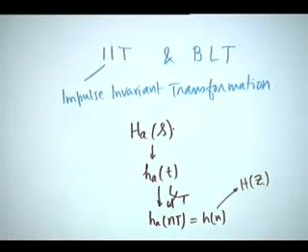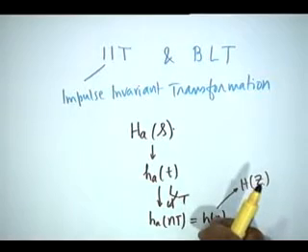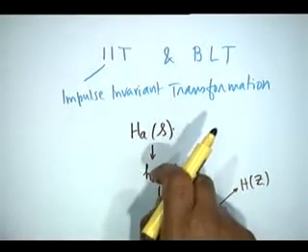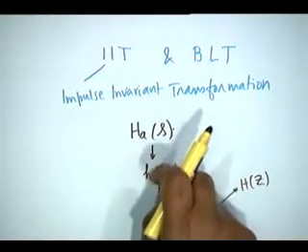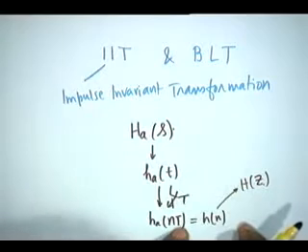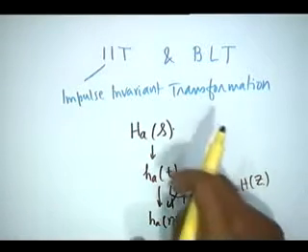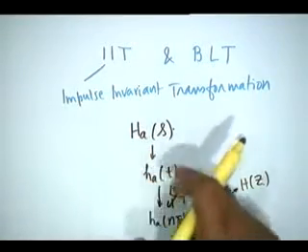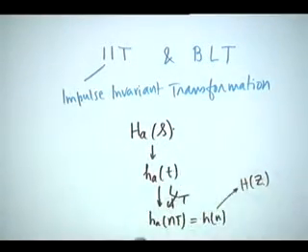That is, the digital filter impulse response is the sampled version of the analog filter impulse response, and if the sampling theorem has been respected in the process, then there should be a 1-to-1 representation. Given h(n), you should be able to construct h_a, and given h_a, you should of course obtain h(n). This is the problem.